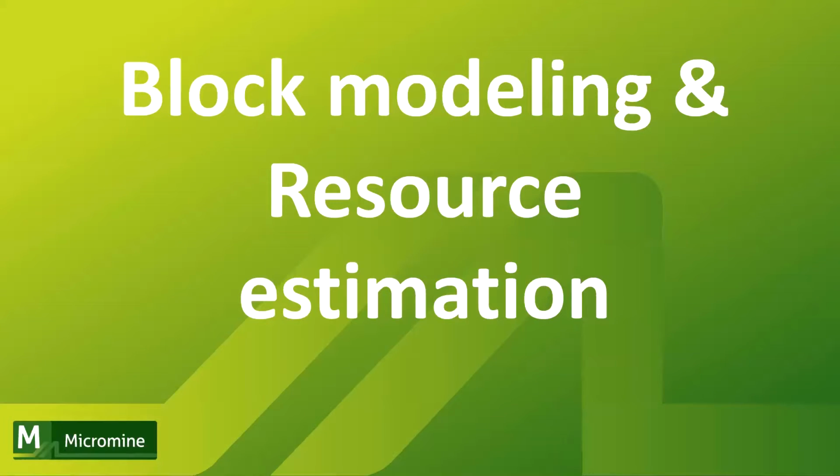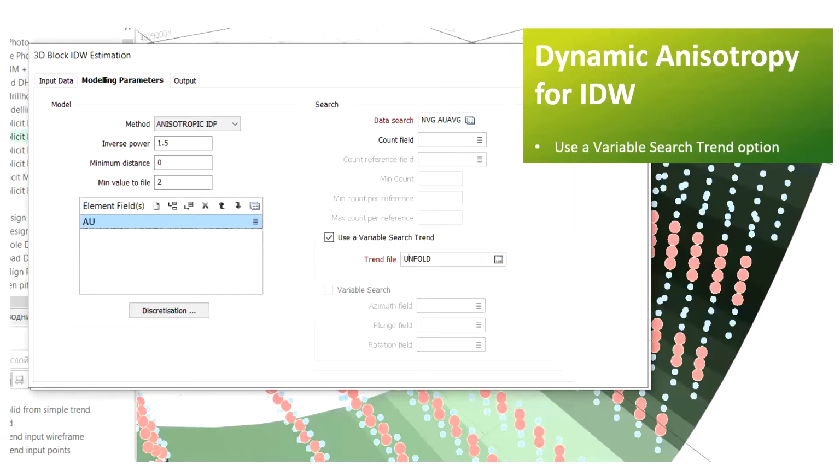Block modeling and resource estimation. On the modeling parameters tab of the IDW form, you can now select use a variable search trend option. The structural trend file you select here is an output of the create unfold trend function in implicit modeling menu.